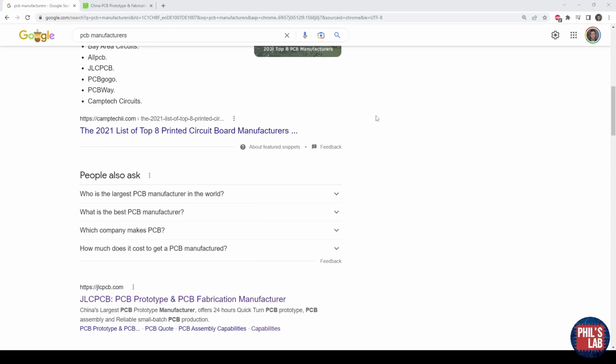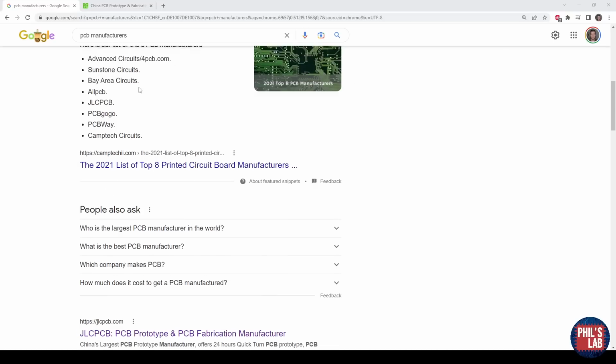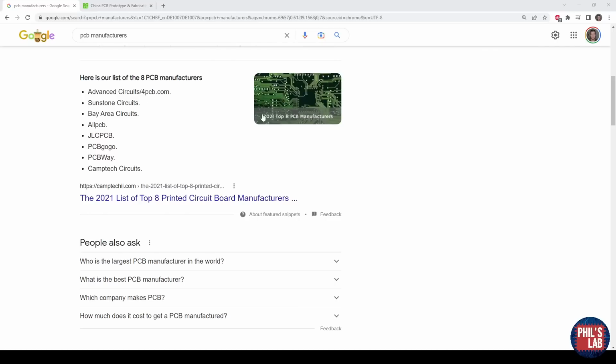This is incredibly important to know before you even start the PCB design, layout, and process, making sure you know what your manufacturer is capable of, both in terms of manufacturing, for example, clearances, drill hole sizes, and so on, but also assembly. Can your chosen PCB manufacturer even do double-sided assembly? Can they assemble 0201 parts, which are tiny, or BGA parts? Do they have equipment such as X-ray machines and so on? This is very important to look at before you even touch the PCB design. And this, of course, happens well before manufacturing.